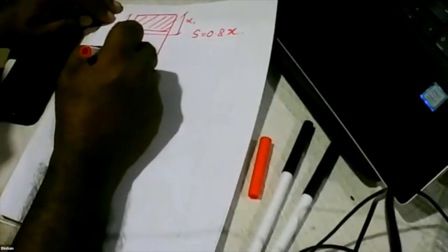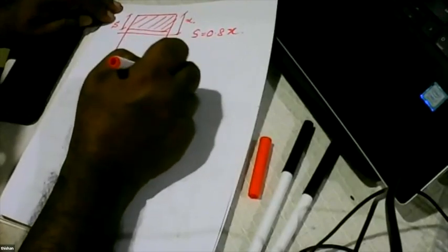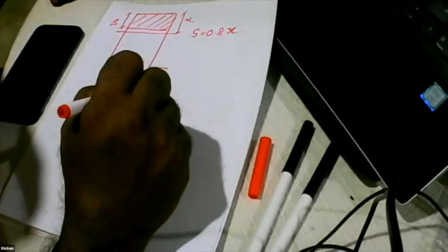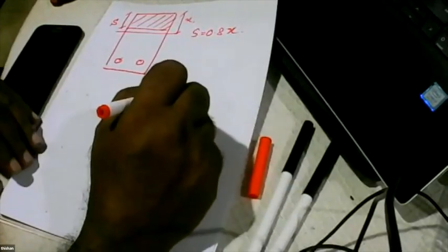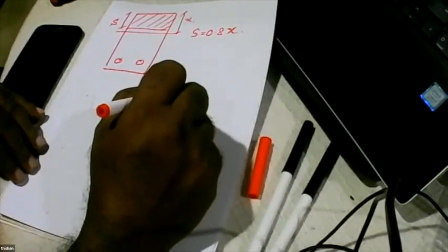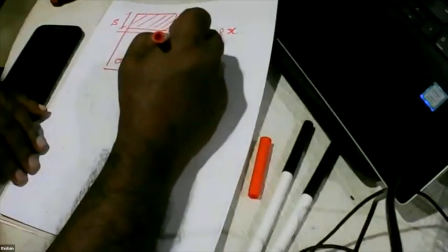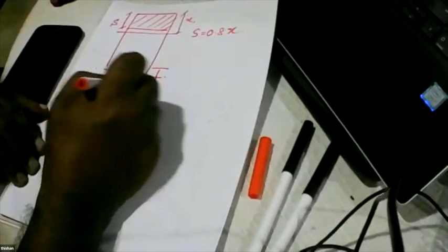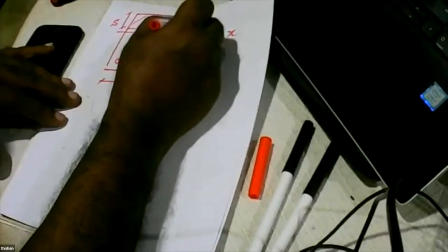And we are going to have some reinforcement here, satisfying the cover requirements for durability. We know the section, we know the breadth of the section, we know the cover requirements, so that means we know the depth D, the depth to the middle of the reinforcement.